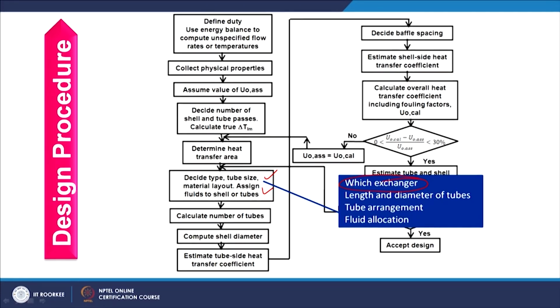And if temperature is more than 90 degrees and the fluid is not clean, it means dirt factors are given or toxic nature of the fluid is mentioned, you should use internal floating head. And if temperature is high and fluid tendency is not toxic, you should choose external floating head.